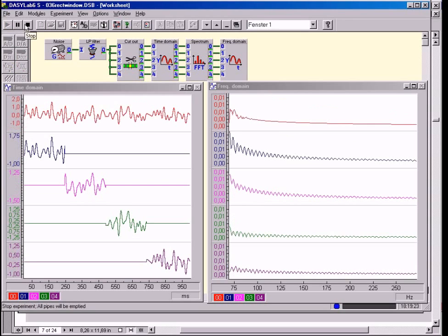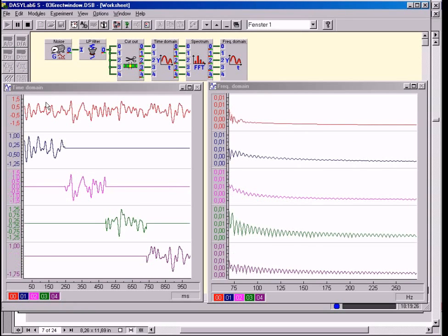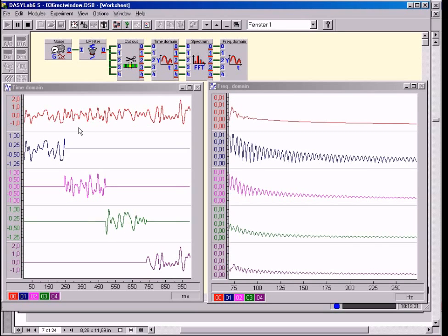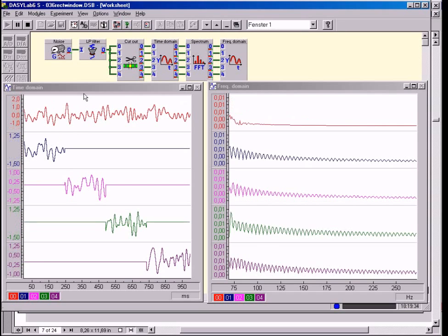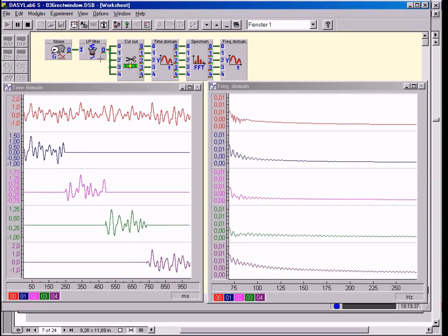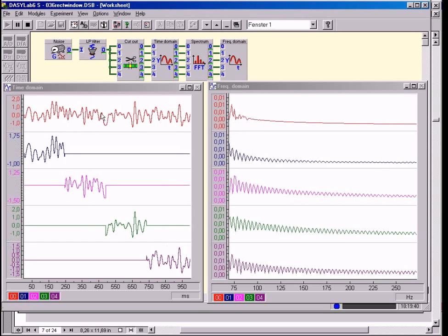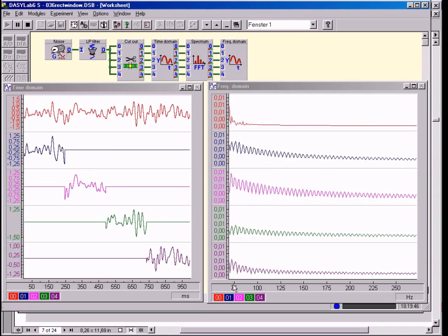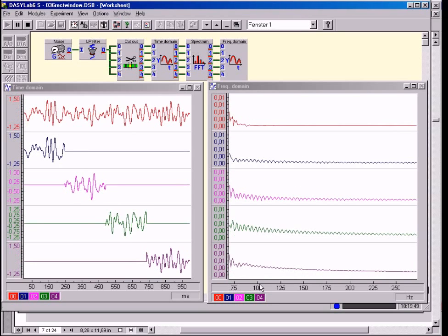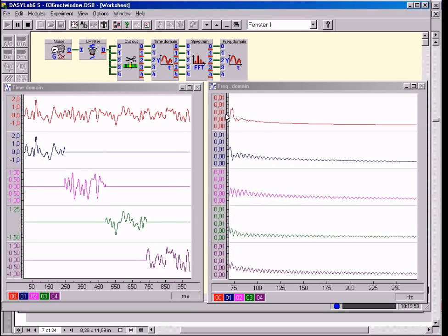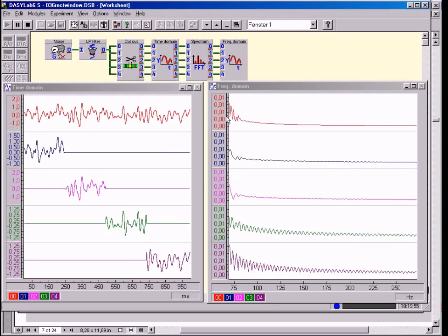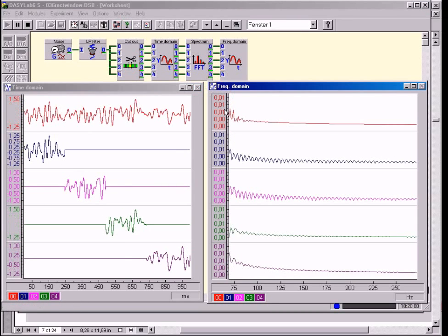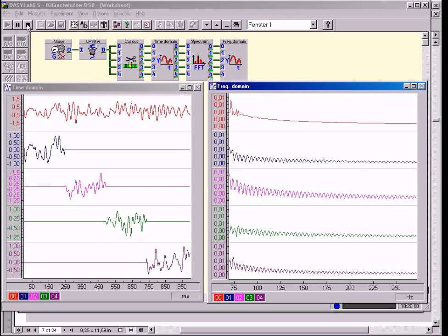The non-periodicity is achieved here by using a noisy signal. This noisy signal is now filtered through a high-quality low pass with a cutoff frequency of 50 Hz. This does not mean that this filter does not let anything through above 50 Hz. These frequencies are damped to a greater or lesser degree, depending on the filter quality. Here we are looking at the blocking state region above 50 Hz, beginning at 70 Hz.